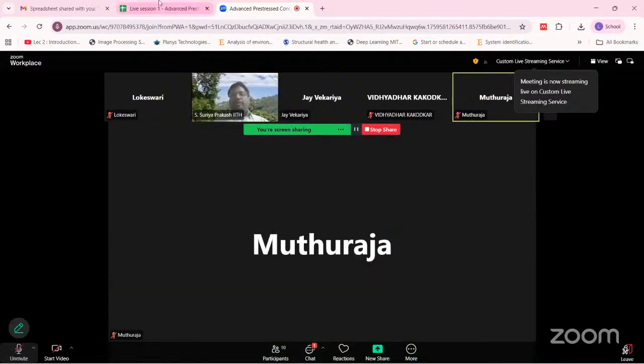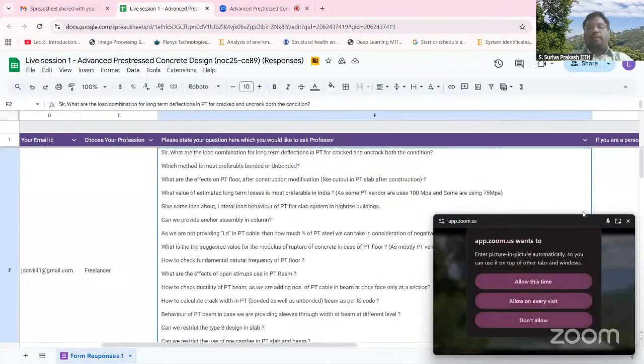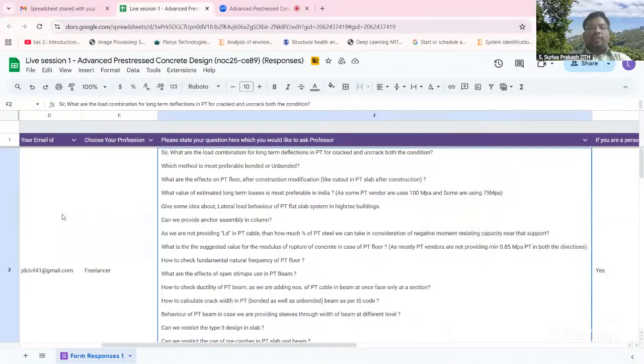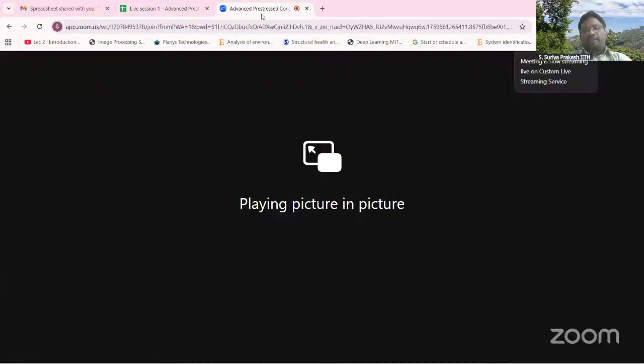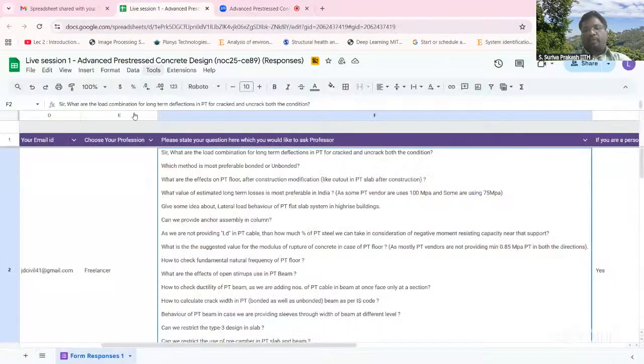All right, so let's go ahead. I feel 100 is a reasonable number. Again, it depends upon the concrete you have. Typically for high strength concrete, we assume that you're going to have a low water to cement ratio, so the creep is expected to be lesser. That depends upon how much free water you have in the mix. But 100 seems to be reasonable, and you have to do the detailed calculations based on the mix design, which we talked about in the losses chapter.